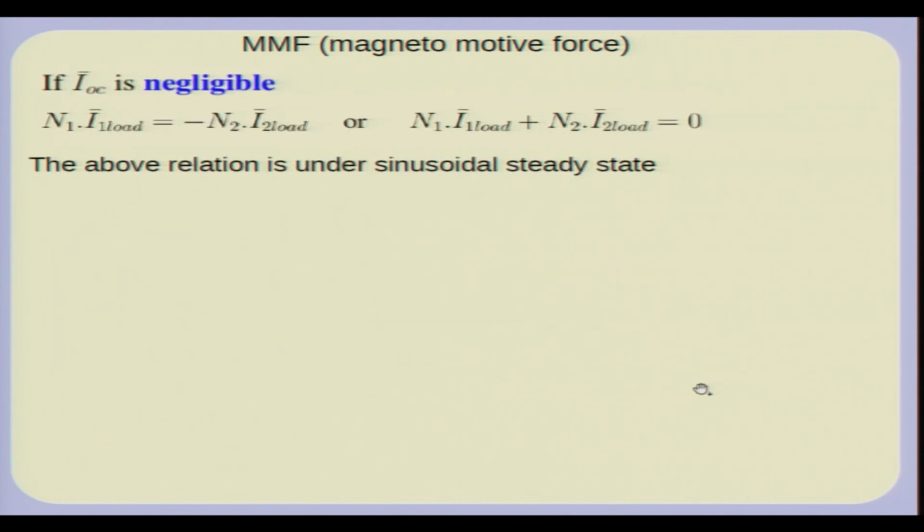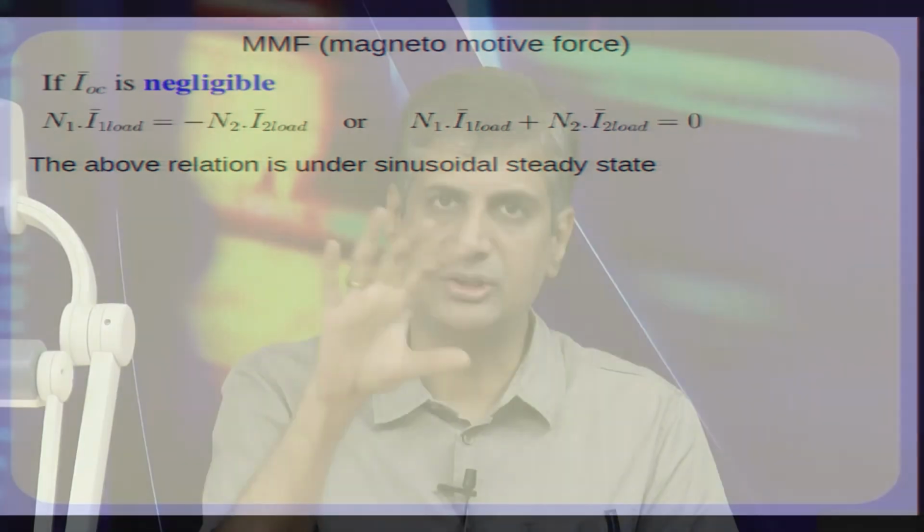Now, one of the important things which again we should remember is all these phasor relationships were derived taking the sinusoidal steady state equations of V1, the relationship between V1, V2 and I1, I2. Otherwise, of course, there is a differential equation, which under sinusoidal steady state we can replace with algebraic equations, a fact which we used quite effectively when we studied sinusoidal steady state circuits.